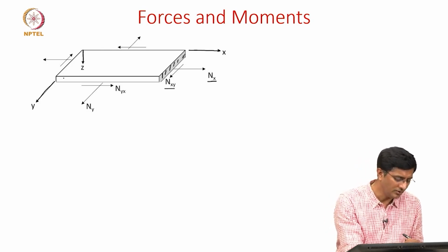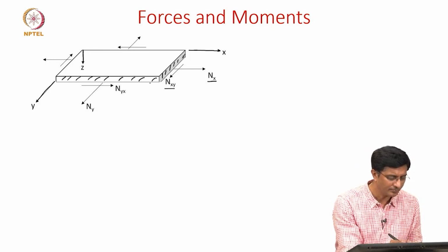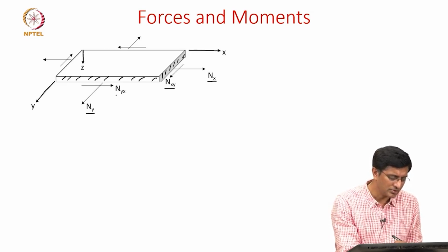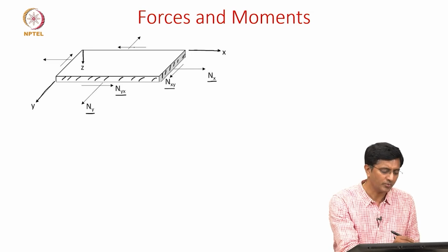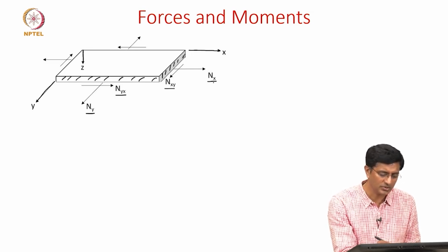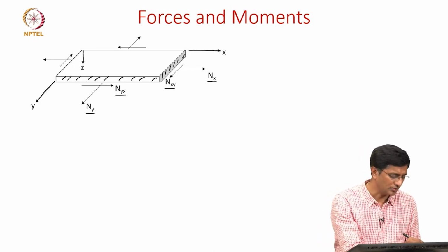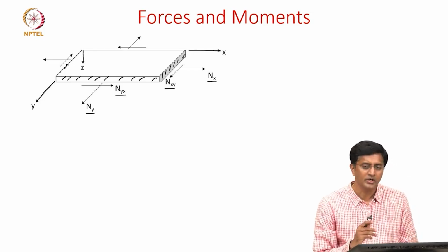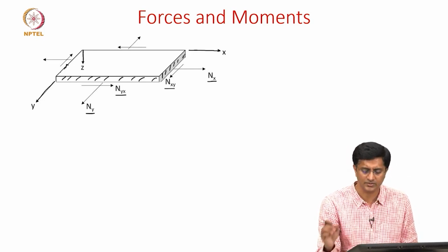Similarly, on this plane, we have the normal force Ny and the shear force Nxy. And the same forces will also be applied in the opposite plane, which is behind. Similarly, these forces Nx and Nxy will be applied on the opposite face, which is shown here. Okay. Now let's see how we can write these forces in terms of stresses.